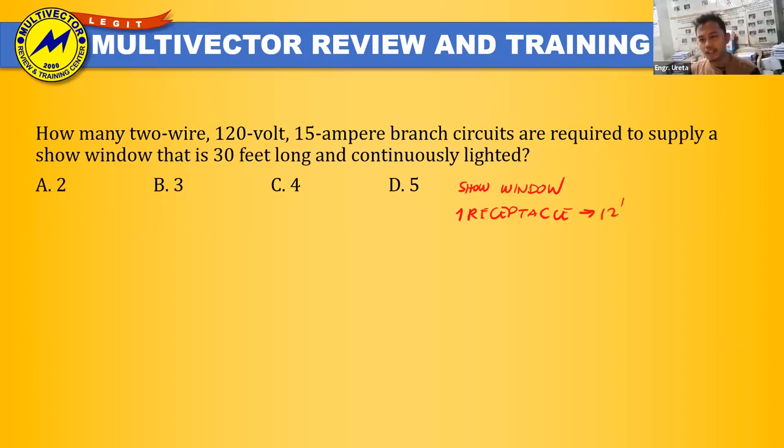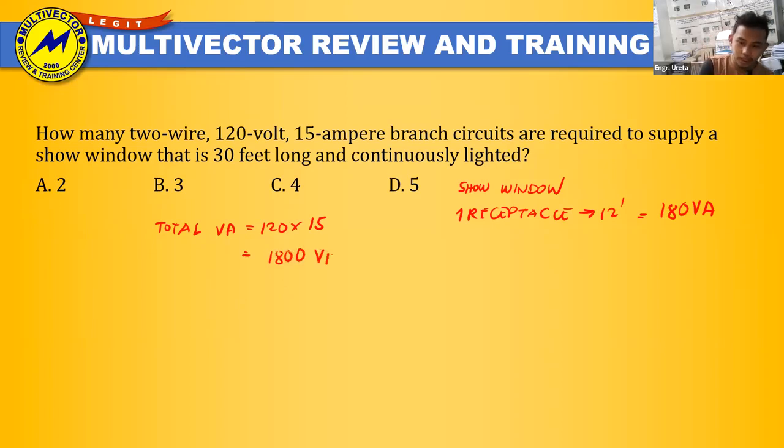Each receptacle, having a branch circuit, has a total of 180 volt ampere. Ngayon, para mahanap natin yung number of branch circuit natin, hanapin muna natin yung total kVA. The total volt ampere is just 120 multiplied by 15 ampere, which is 1,800 volt ampere.